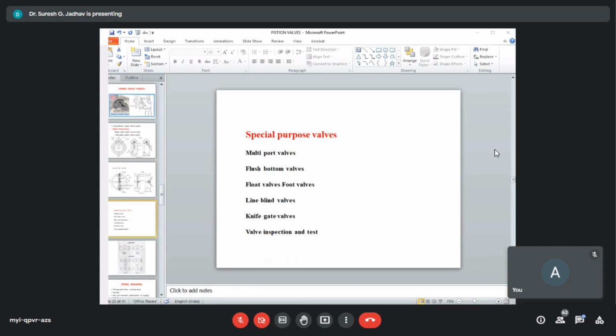For hydrostatic tests, the test fluid shall be water at ambient temperature unless the use of another liquid is agreed. The use of high chloride containing water should be avoided. The water may contain water soluble oil or rust inhibitors. Fire test is a destructive test and carried out only in exceptional cases when specified. The arrangement and test shall be as per API 607 or BS 6755.